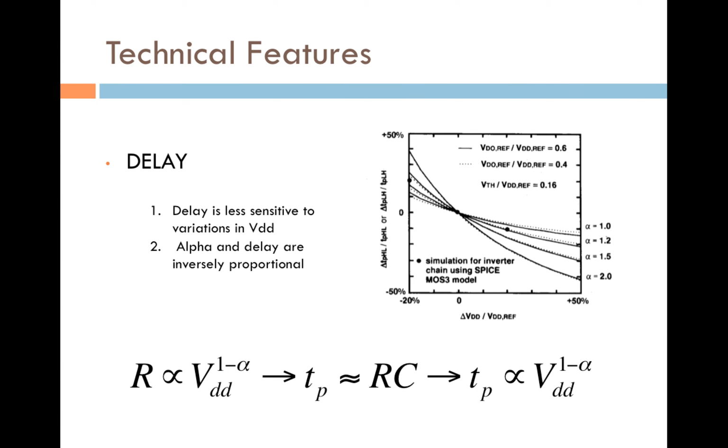All the contents mentioned before and the new physical phenomena that we are facing have implications relating the behavior of the transistor. First, we take into account the classical delay definition. This is the time difference between half VDD in the input and half VDD in the output, where VDD is of course the supply voltage. We must say that in overall, when alpha gets smaller, the delay increases. So delay and the alpha value are inversely proportional.